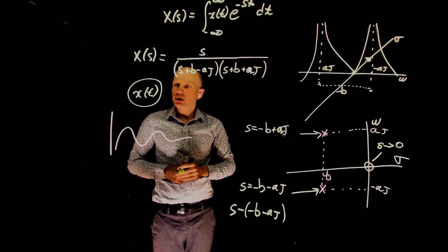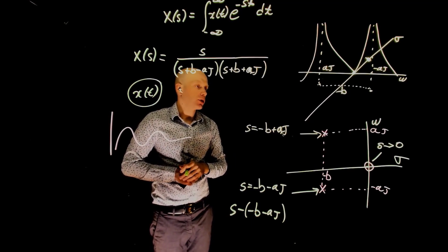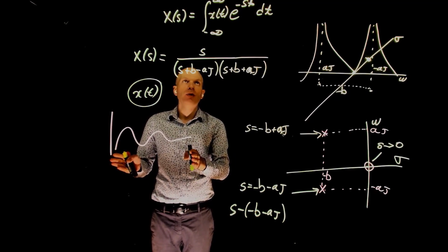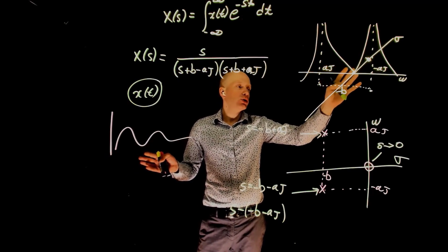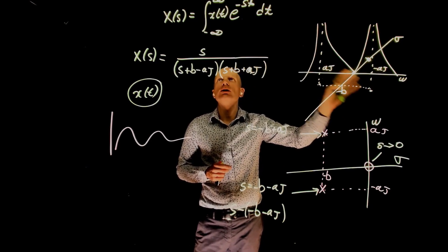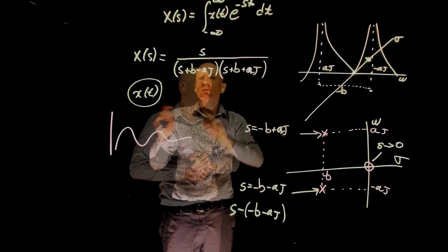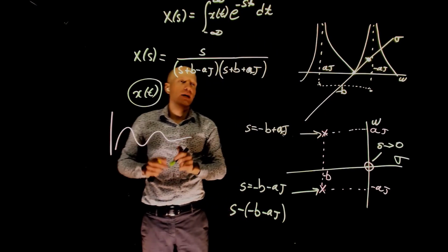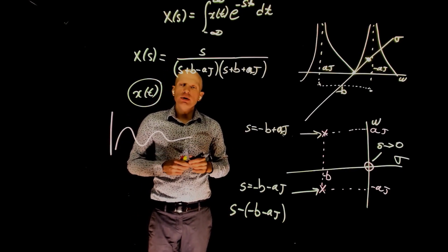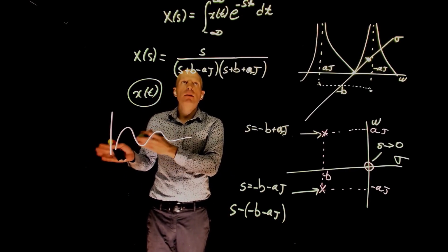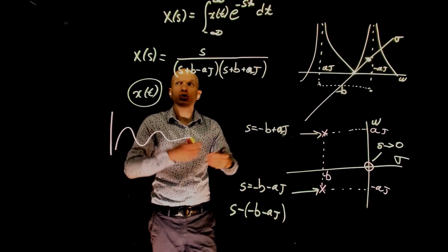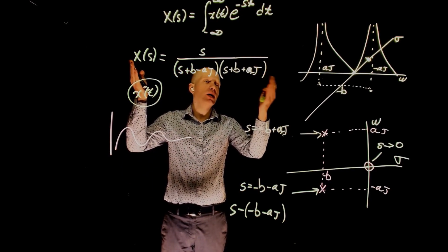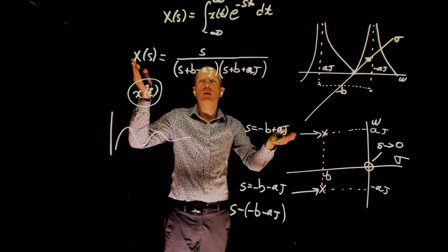Now the way we approach this is not the traditional way we see in the textbooks. We went from having a signal to now decomposing that signal into this 3D representation here on the S-plane with the magnitude of this transformation, to having the Laplace function that represents that signal. But in reality, what are going to happen is that we have a model. The model will give us a differential equation. From the differential equation, we'll get here, once you take the Laplace transform of that differential equation.